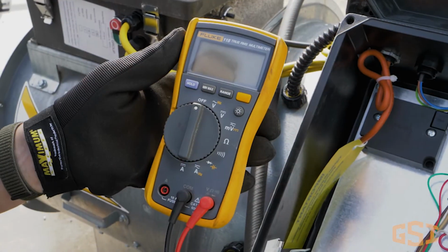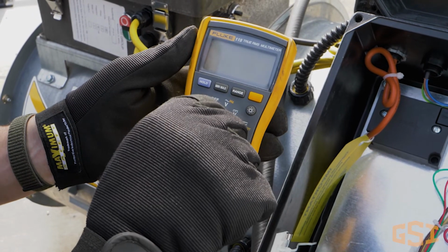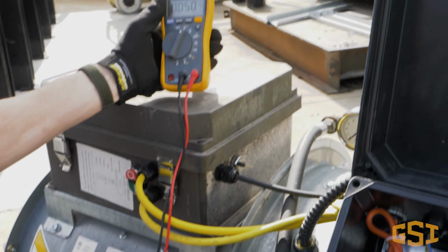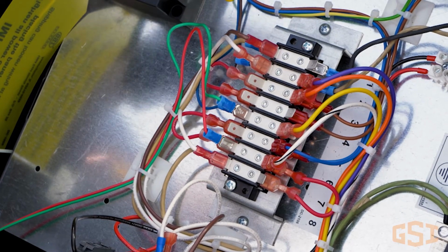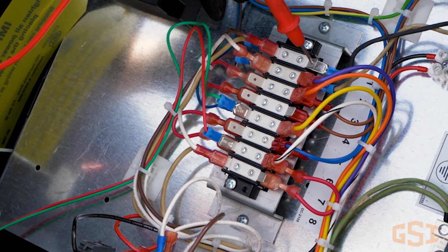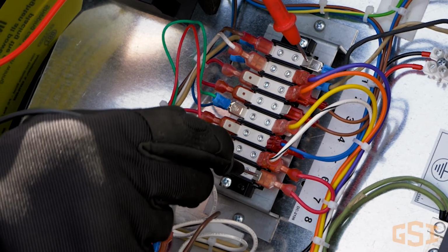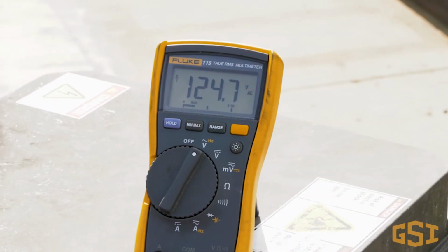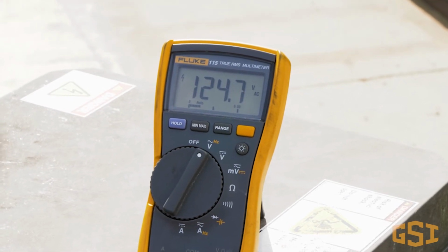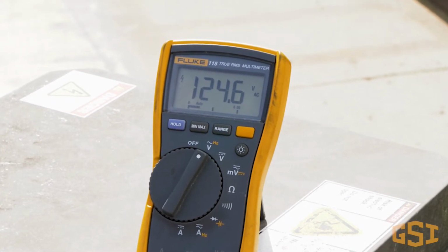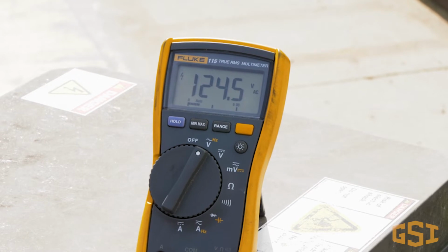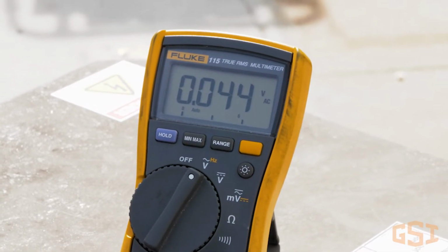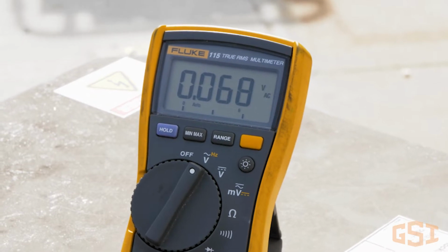With the fan running and the burner switch turned on, use a voltmeter set to AC volts to check for power. Put the red probe of your voltmeter on terminal 1 and the black probe on terminal 8. You should read approximately 120 volts AC. Be particularly careful when performing this check, since power will not be locked out during this step. If you do not have 120 volts AC, we can diagnose the reason using the wiring schematic.